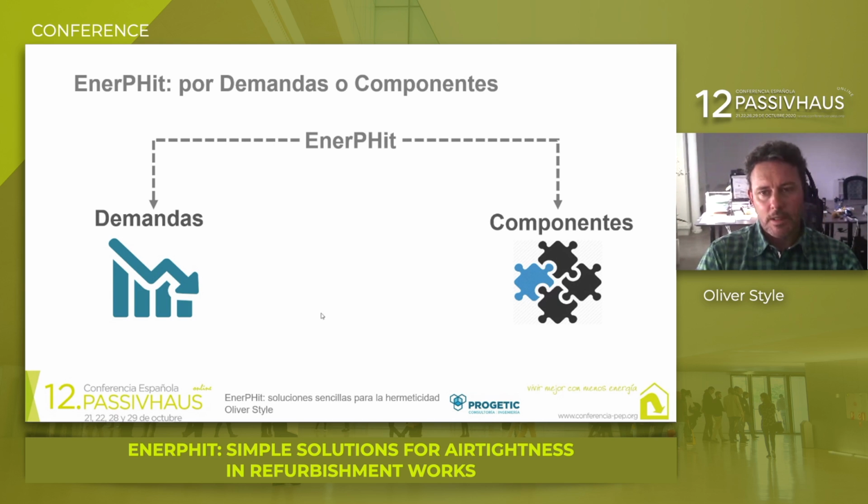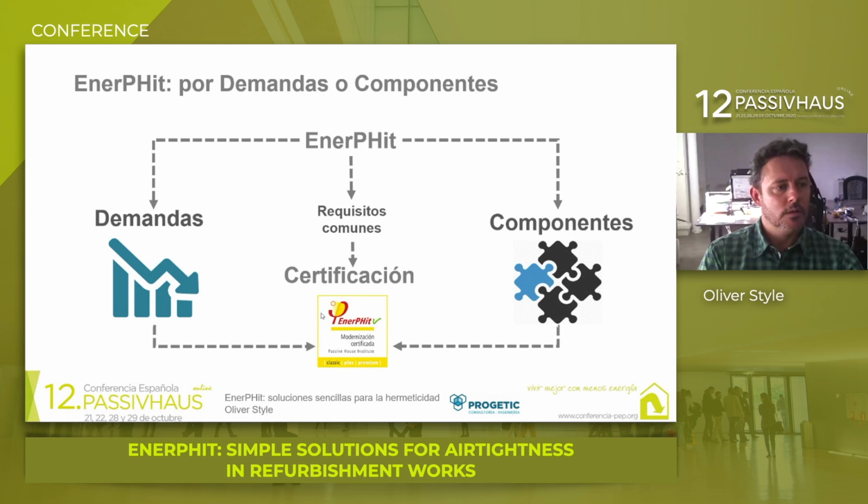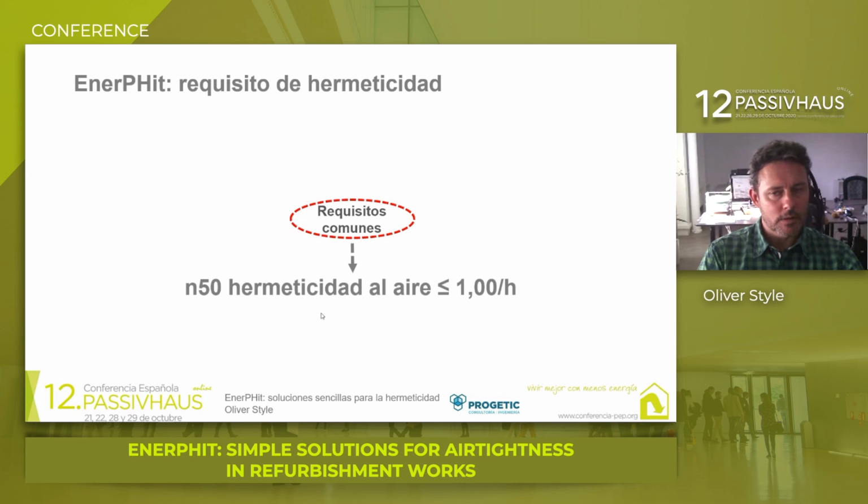The demand-based approach focuses on performance, on features similar to the requirements for passive house in new buildings, whereas the components-based approach is prescriptive. In other words, the different constructive elements must comply with maximum thermal transmittance limits. Solar load must be reduced to avoid overheating problems. And then there are a series of common requirements for both approaches, including airtightness as a requirement.